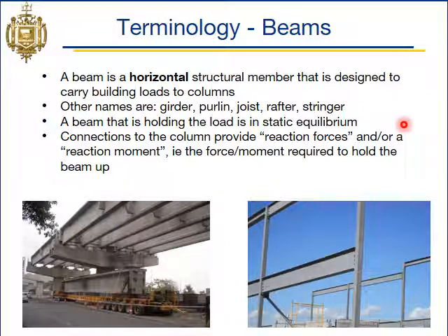And all beams are essentially connected to a column, and that column provides what we call reaction forces. So that's the focus of this class here, is to calculate reaction forces where beams are connected to columns. There may also be a reaction moment where the connection's at, depending on the type of connection.